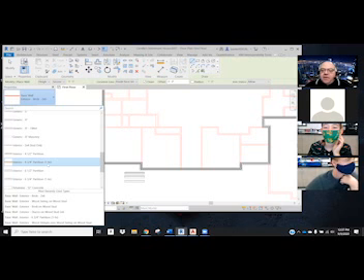Residentially, we've only got about 45 minutes. So we have a little bit less time to get out of the building, but we're dealing with fewer people. And the building code is set that it's to save the many and not the few. It's very cruel that way. If we burn a house down and we lose a family, society can go on. If we lose a 110-story building and lose 3,000 of the most important brains in the world, then society is affected. And that's how the building code thinks. So we have to kind of keep that in mind. It's kind of cruel that way.